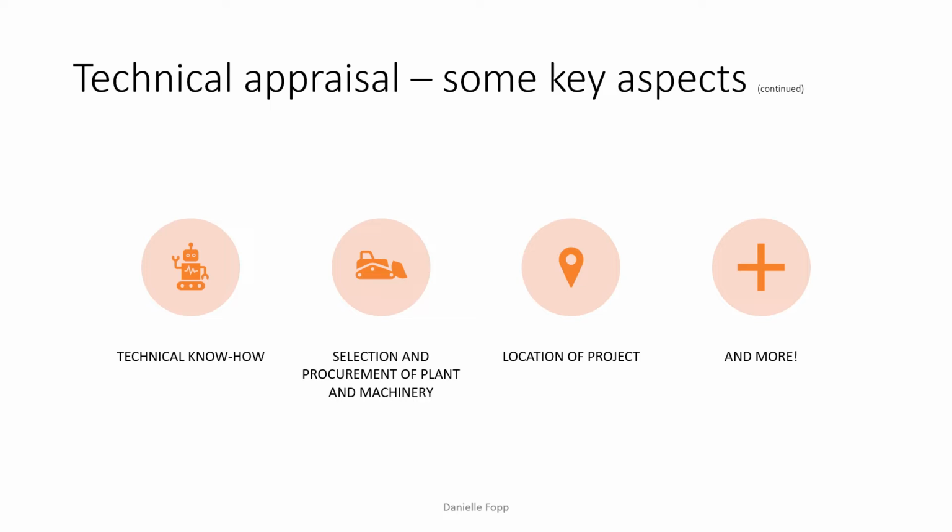To do this, we also take a look into the consideration of the output planned or the size of the project. We also need to look at the machine hours required for each type of operation, the capacity required, and also making necessary allowances for if there's a machinery breakdown or if someone needs to go into maintenance. Workers need to rest, set up time for machines, time lost during change shifts, etc. And we also need to make sure that there is machinery available in the market, particularly if we're hiring the machinery, with regard to the capacity chosen, and it's equal to or just above the capacity theoretically arrived at.